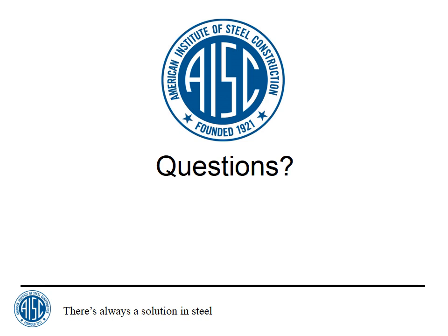And even if you have a special case 4, there's still no normal forces on the web, because by the time you get there, they dissipate. You have normal forces out where the bolt lines are, but by the time you get to the face of the column web, there are no axial forces, unless there's a transfer force. There's some kind of a force that's coming from the other side of the column. Then you would have to consider some sort of a yield line, and there's so many variations on that that I think you need to look at each case on its own merits.